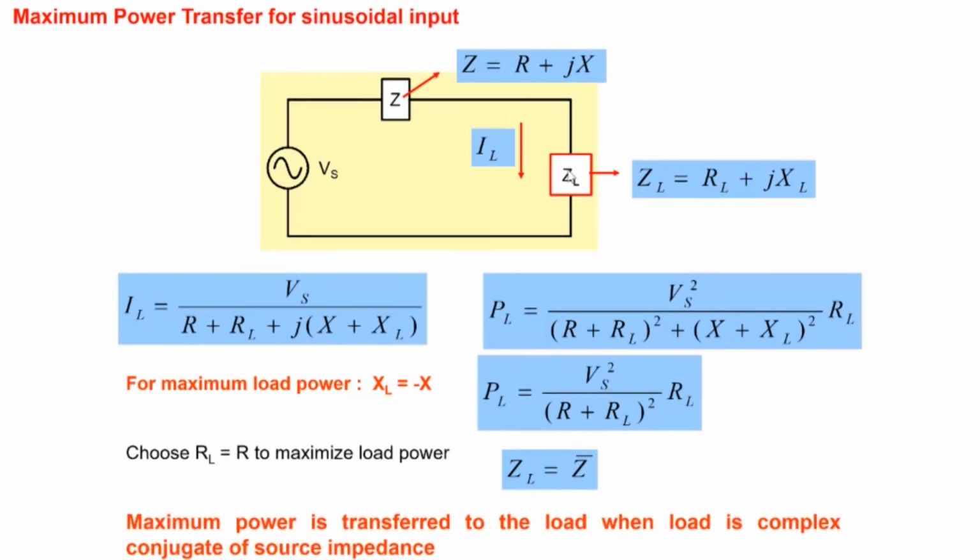So that's a generalized maximum power transfer result when we have the concept of phasors. When we have inductors and capacitors in the circuit, we have this general result: choose ZL to be the complex conjugate of the Thevenin's impedance.